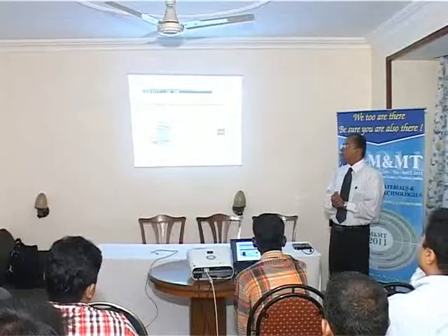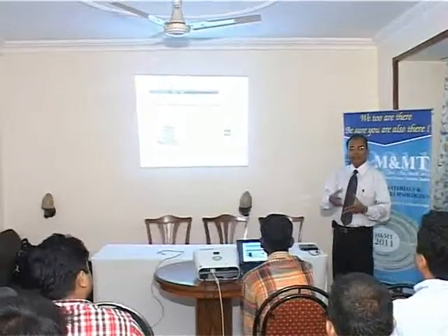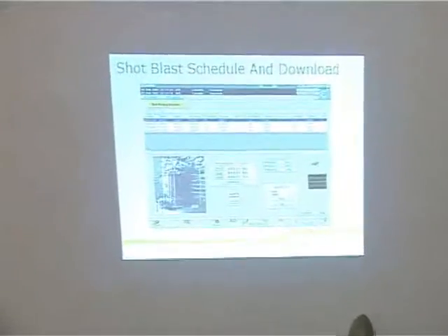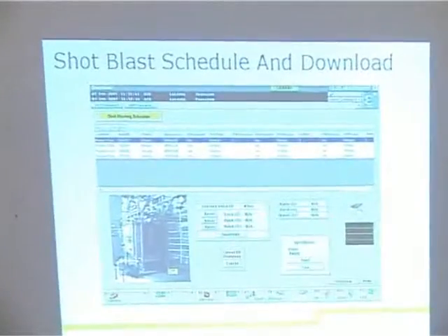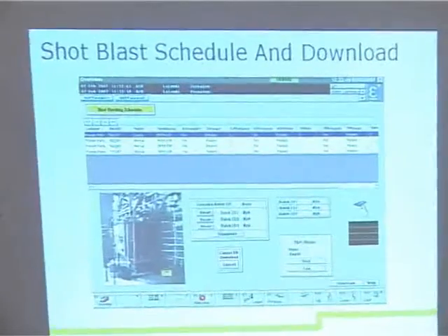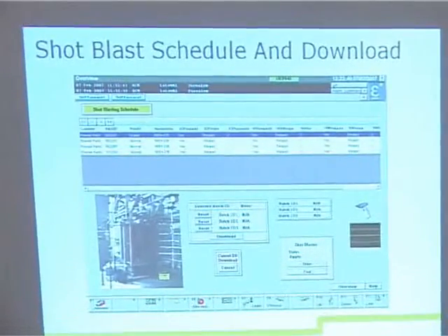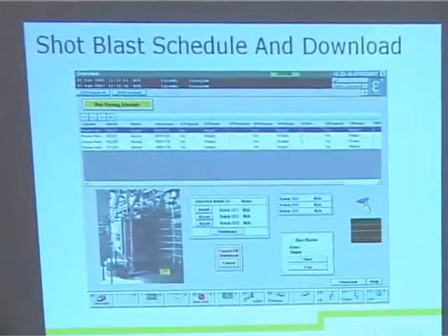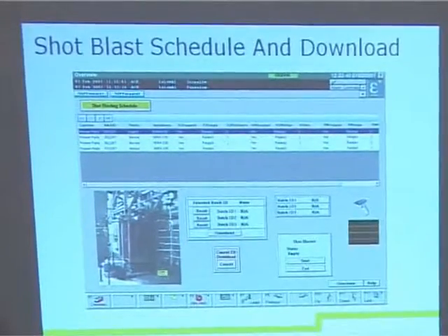Now what happens is, let's say we talk of a pellet heating, we talk of various charge, the actual temperature and the furnace temperature. So let's say even if you talk of a big furnace, you can have 1, 2 or 3 zones depending on the way you have designed it, and the sensors are there in place, but are those sensors actually close enough to the charge being heated?